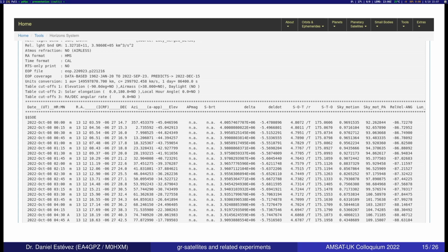If you compare the position against the backdrop of stars, it moves slowly. So if you use right ascension and declination and adapt your station to control the pointing in terms of right ascension and declination, you need to do fewer updates. But then, of course, you can also see azimuth and elevation, and we can see this is today in the morning, so the spacecraft was below the ground, but at some point it rises on the horizon, and it will spend 10 or 12 hours above our heads.